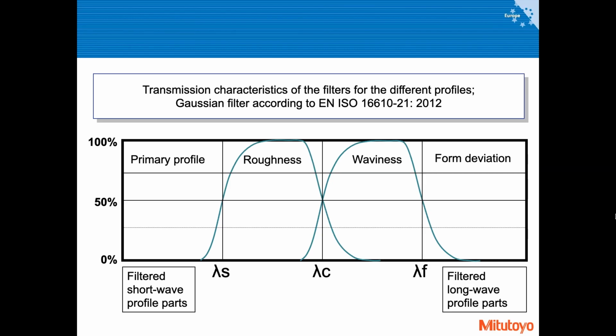And I think one of the most important points you need to take out of today's presentation is, if you are about to deal with surface texture or roughness measurements at a certain point of your life, you really must remember that these cutoff values, which are represented like this, lambda c over here, are very crucial in order to do your measurements right.